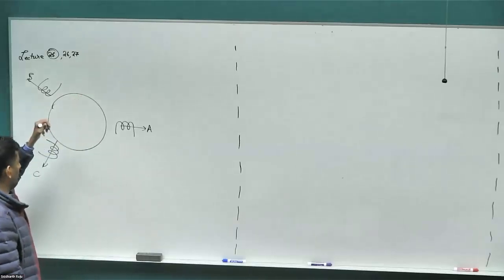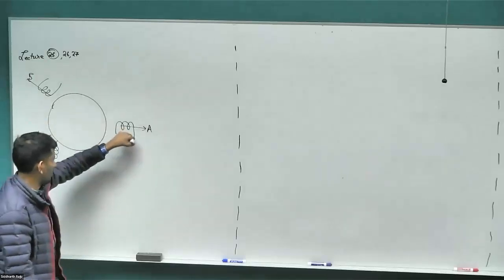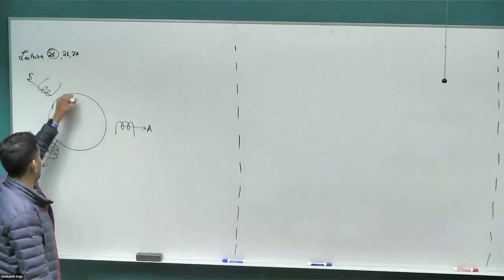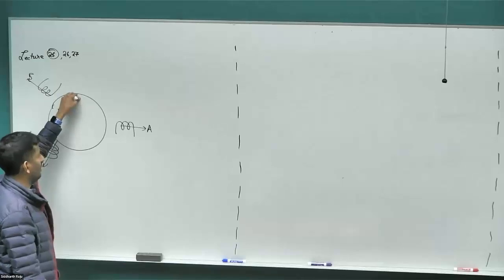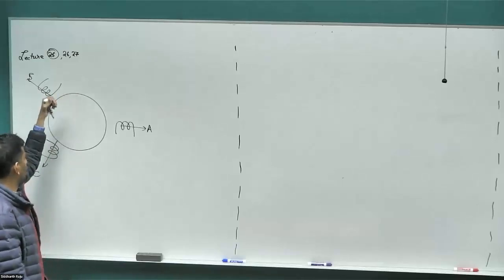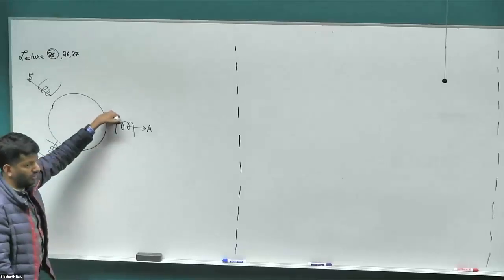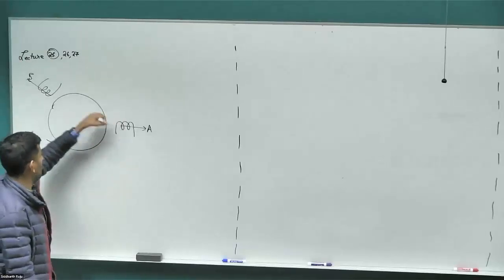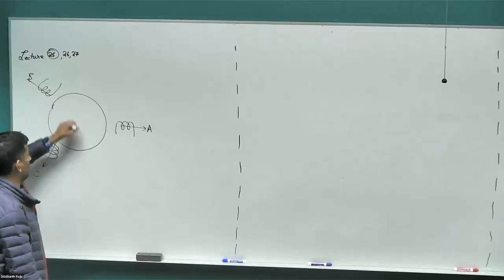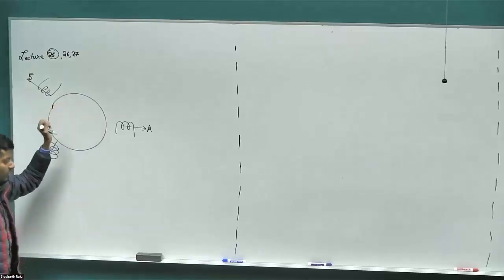And as far as the conductor density is concerned, if I draw this loop around this direction, the maximum conductor density, conductors for A phase is 90 degrees away from it, right? An easy way of visualizing this is if I form a loop like this, the B field of that loop will be along this direction. So if the B field is maxima here, the conductor density would have to be maxima perpendicular from it, right? So this is what we have.